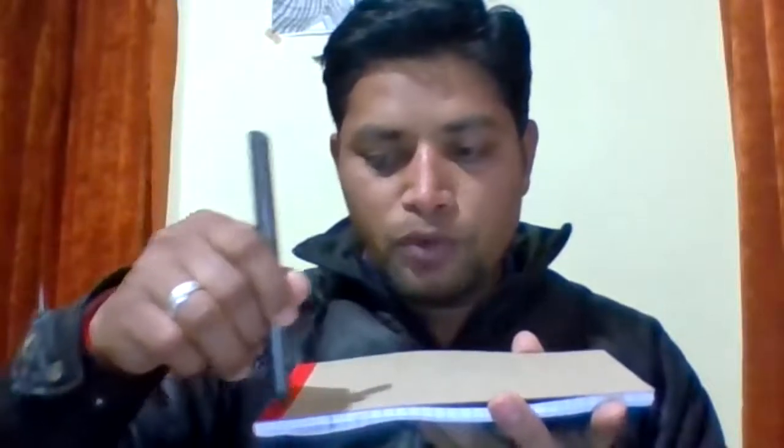Okay, so here we are providing the feed to the tool. Now we are moving in this direction, so the material is removed. Whatever the width is there, if this is again 50 mm, and 1 mm of width can be removed in a single pass, let's say 1 mm, then how many total passes will you have to make? Total 50 passes will have to be made.